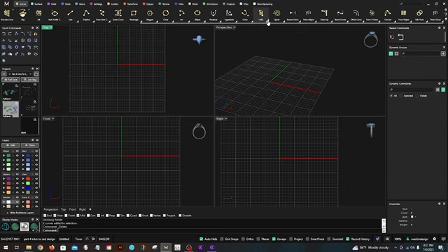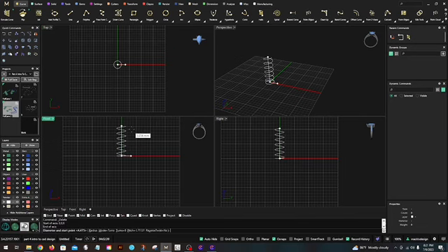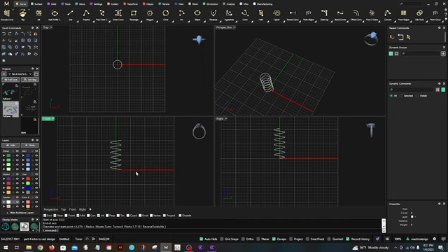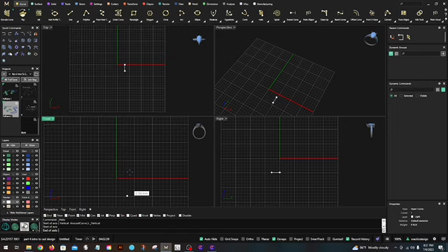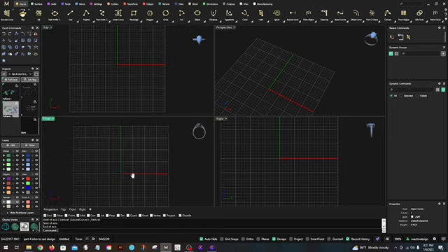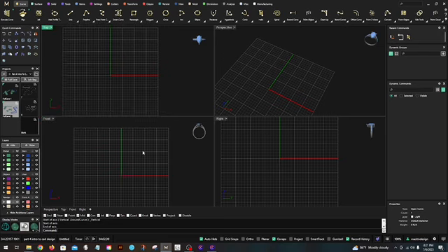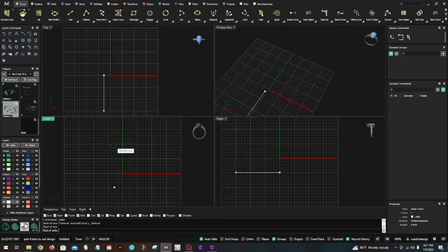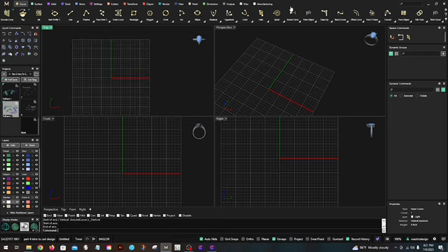All right, next, helix vertical. Okay, so that just means vertical, which is kind of interesting that they specify that, because you could literally just go in this viewport. Oh, it doesn't let you. Oh, that's why they specified. A lot of times the commands will allow you to go in any viewport, but this one literally does not let you do that. So if you want to go vertical, you have to specify vertical in your helix.